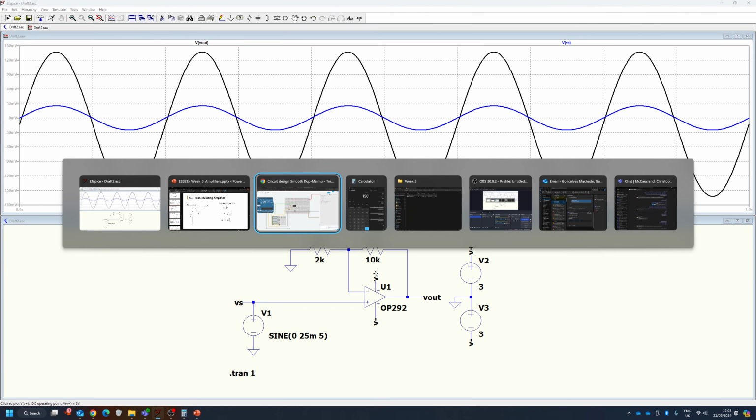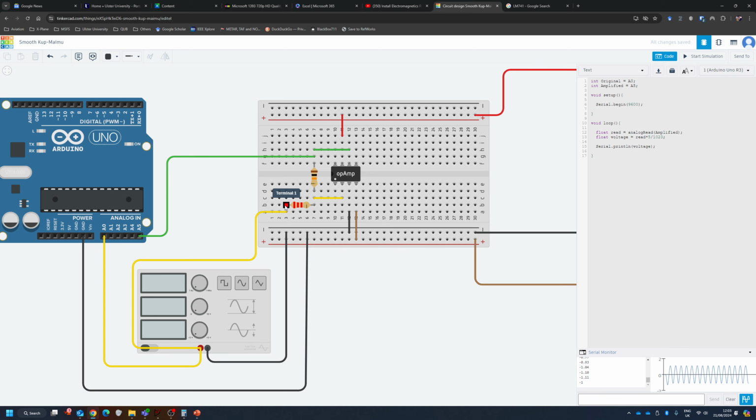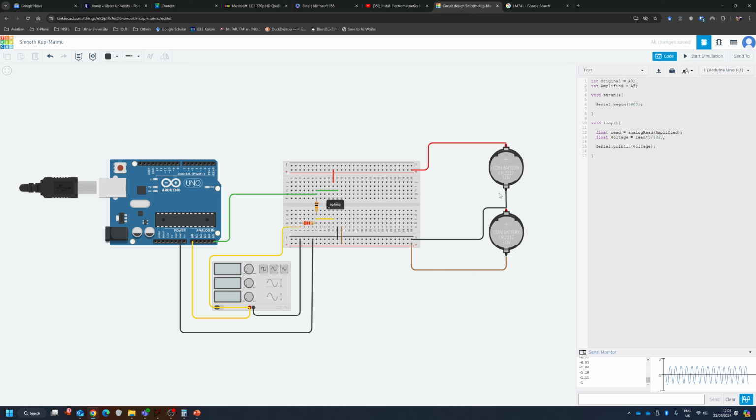So this resistor here goes to ground, and my yellow wire goes into in plus, and my ground doesn't go into in plus. So that's it. Remember, this is a tricky part to get the batteries working well, but just follow this schematic here and you should succeed both in here and in the lab.